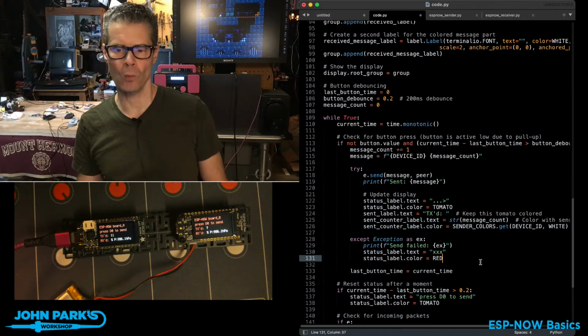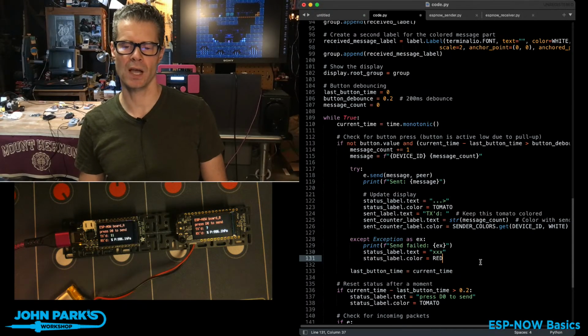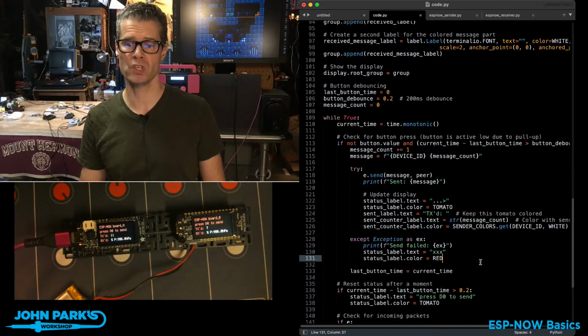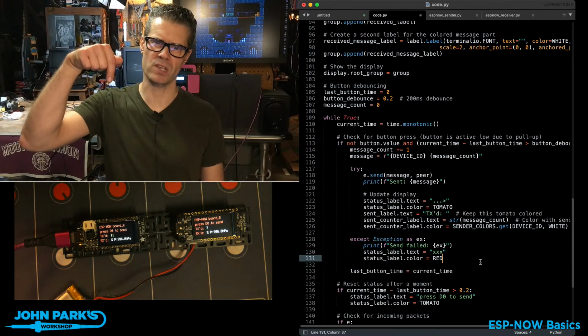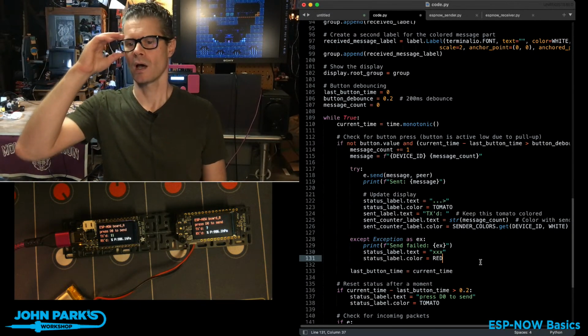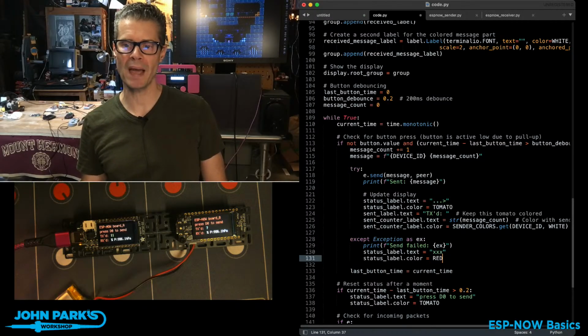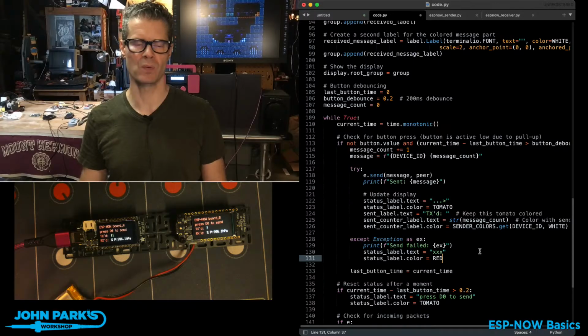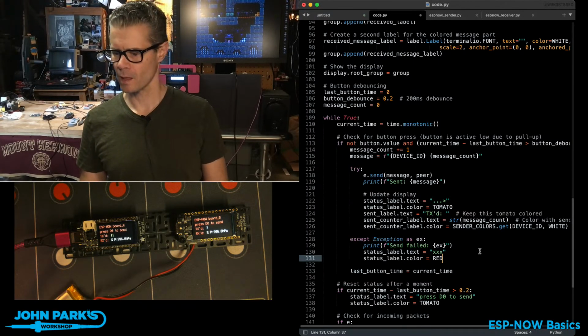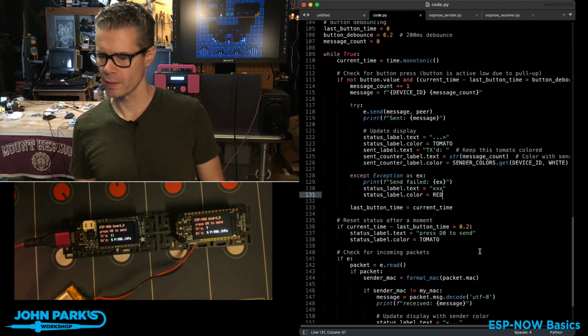That's a nice, straightforward way to do it. I've actually done some CircuitPython on a couple of other ways. One is there's a debounce library that's really convenient to use. That also allows you to do some long presses and double presses and stuff. Other way I really like to do it is with the keypad library, which has debouncing built into it. So look for the Learn Guide on keypad, or look for debounce. And we have Learn Guides on those. We also, like I said, I have some CircuitPython Parsecs. Great question. Thanks, Ed.